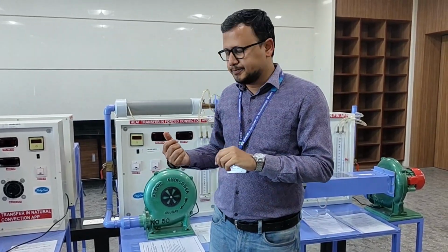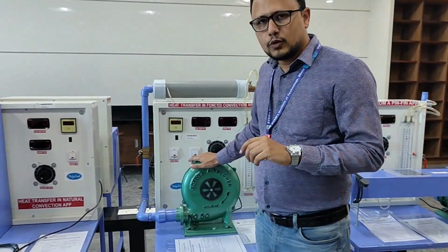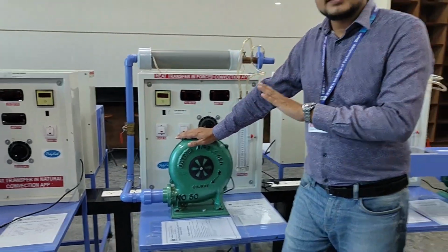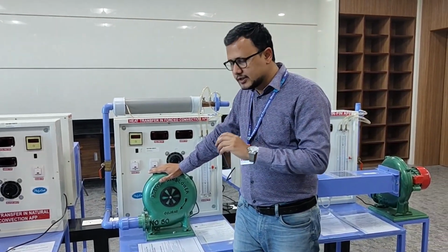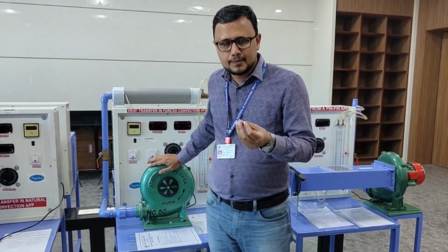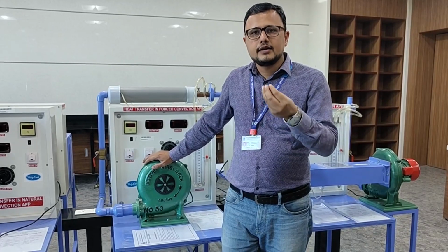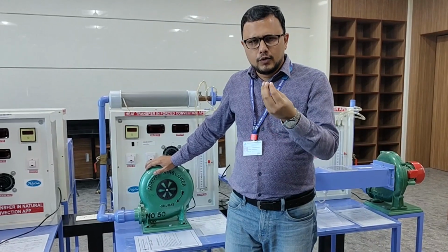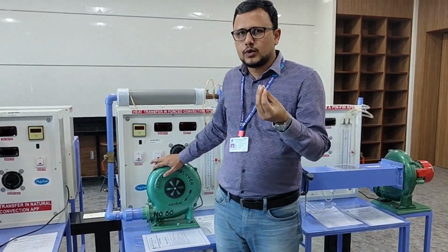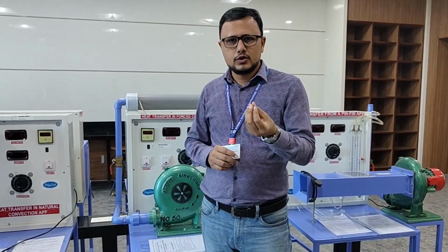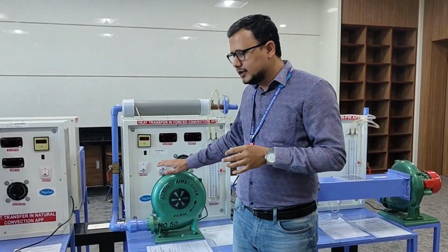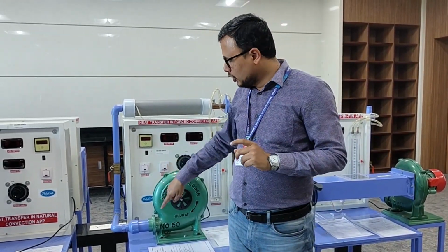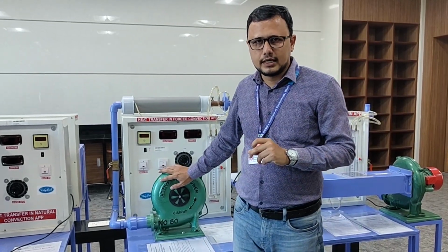Now we will get to the setup. So we have created forced convection with the help of this air blower. Remember, this is an air blower. This is not an air compressor. Its function is not to create very highly pressurized air. Its function is to create air having a larger volume flow rate, to provide higher flow rate. For example, if atmospheric pressure is 1.01325 bar or 101.325 kilopascal, then this may generate pressure of air hardly up to 1.1 or 1.2 bar. But volumetric flow rate through the system will be much larger.